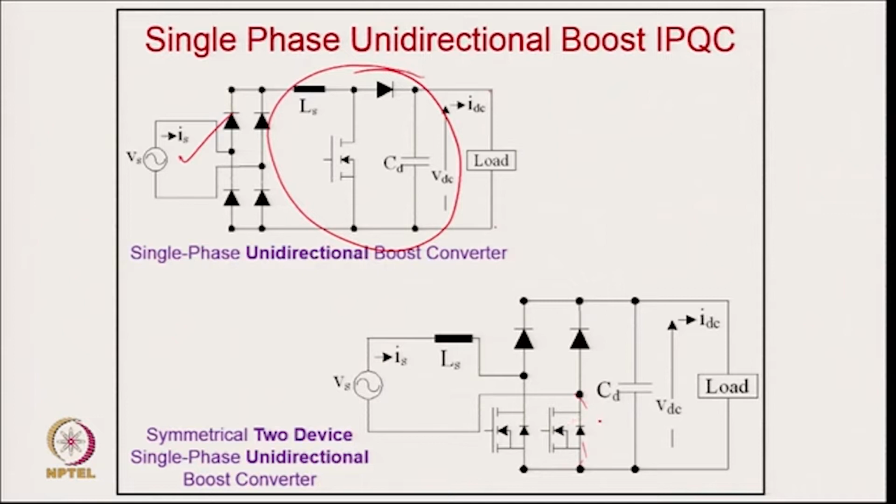So, we also call this a bridgeless configuration. The benefit of this is that the inductor is moved to the AC side. So, the design of the inductor becomes quite simple because it is an AC inductor now. Another benefit is the drop of one device: if current is flowing, it flows through 3 devices here, but here it is only flowing through 2 devices. So, you can say converter losses are also reduced by approximately 50%. So, that is another benefit.